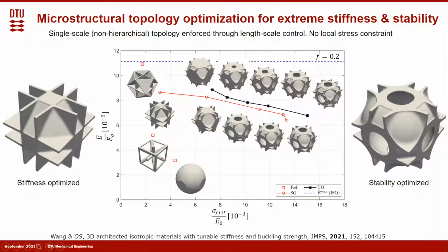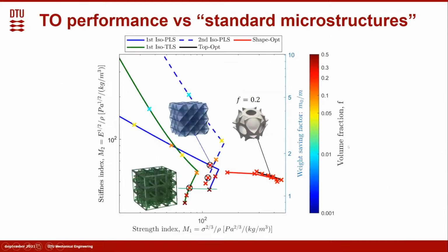This image shows the stiffness optimized microstructures. One may notice actually it's not stiffness optimal, it's sub-stiffness optimal. It's due to the length scale we imposed in the optimization for 20%. It's much higher than the plate thickness. This shows the buckling strain optimized microstructures.